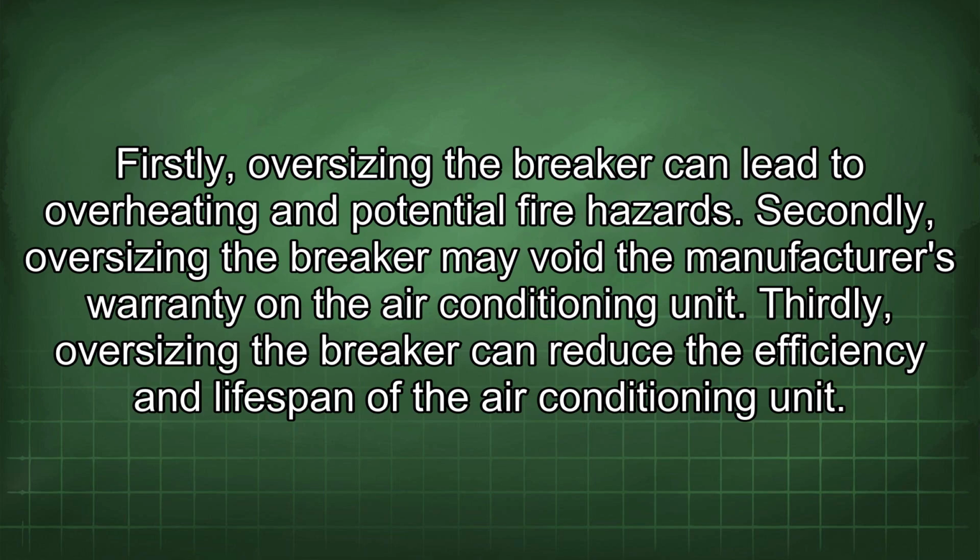Firstly, oversizing the breaker can lead to overheating and potential fire hazards. Secondly, oversizing the breaker may void the manufacturer's warranty on the air conditioning unit. Thirdly, oversizing the breaker can reduce the efficiency and lifespan of the air conditioning unit.